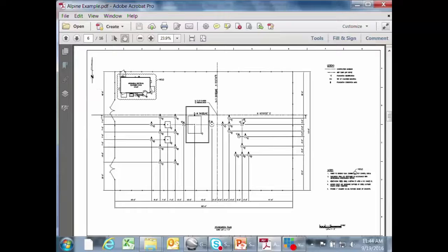Now here's a question for you. How accurate do these drawings have to be? Within what distance? I mean, we're not perfect. We can't make something absolutely accurate. Just can't do it. Do you know the dimensions that we worry about in a substation? We get everything to 1/8 of an inch. And if you have it within 1/8 of an inch, there's enough slack in the bolt holes that everything should be able to fit on the foundation, and everything should be able to work out at that point. So anyway, this is in the development of the drawings.